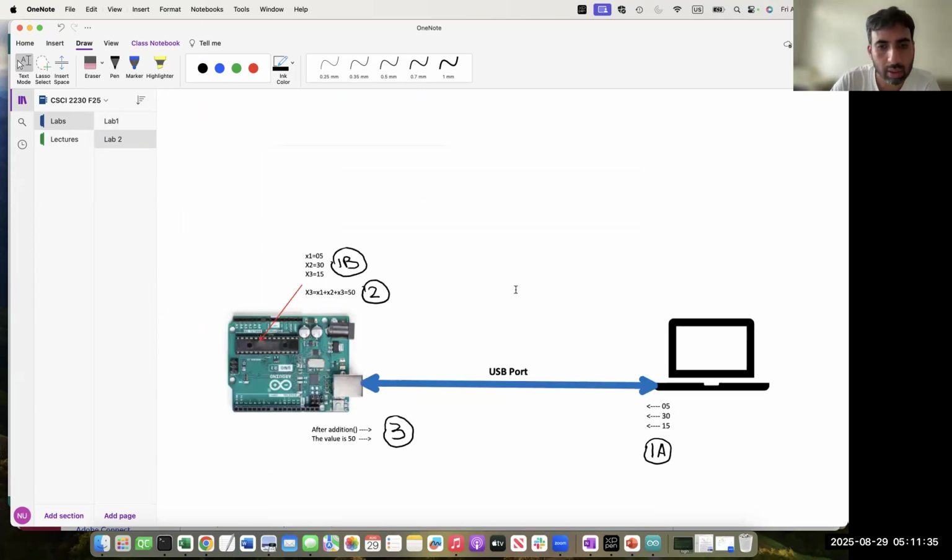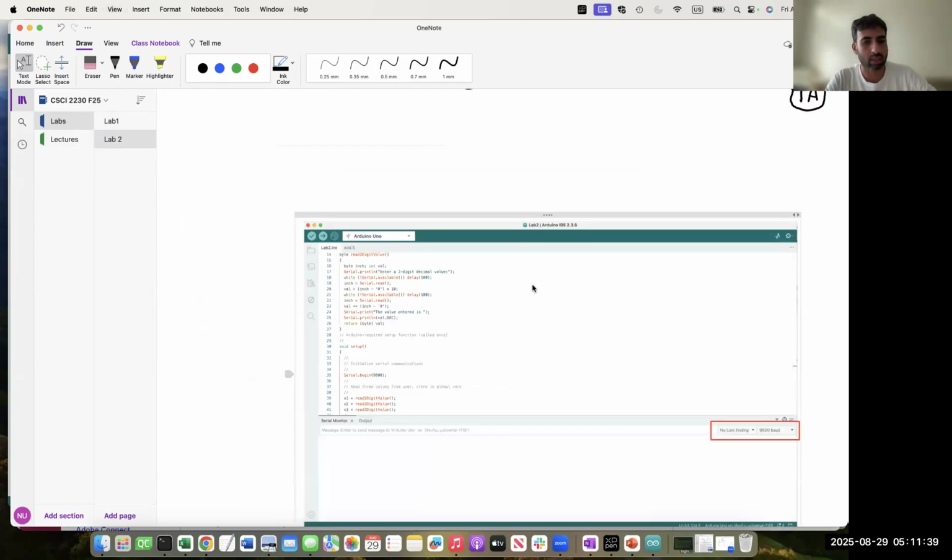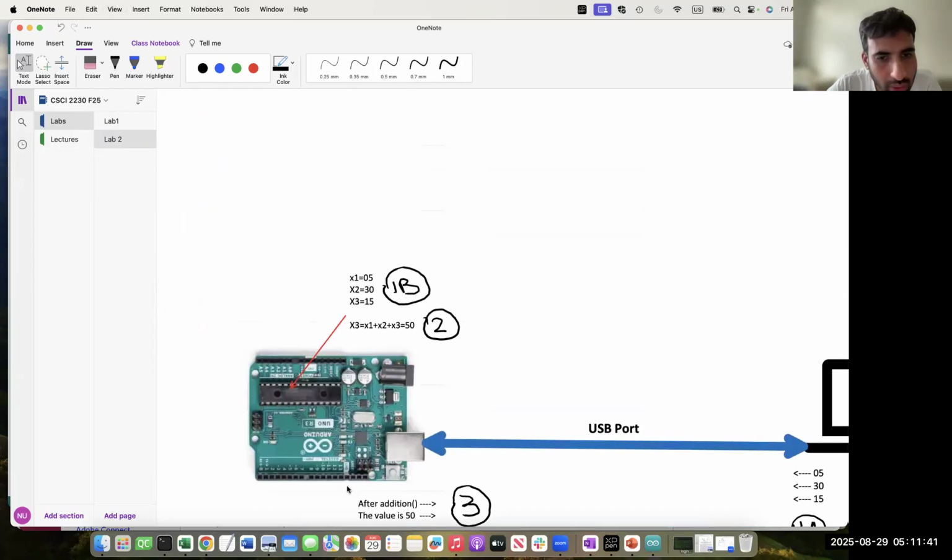So here you have these pins like 0, 1, 2, 3 up to pin number 13. So the LED is connected with pin 13. Actually this pin 13 is pin number 5 on port B of the microcontroller. Remember in the first lecture I explained the pin mapping between the AVR microcontroller and the Arduino board. So pin 13 is actually pin 5 on port B, right?